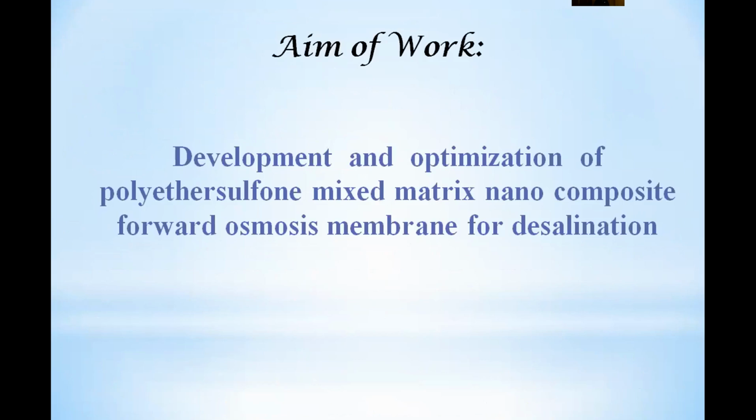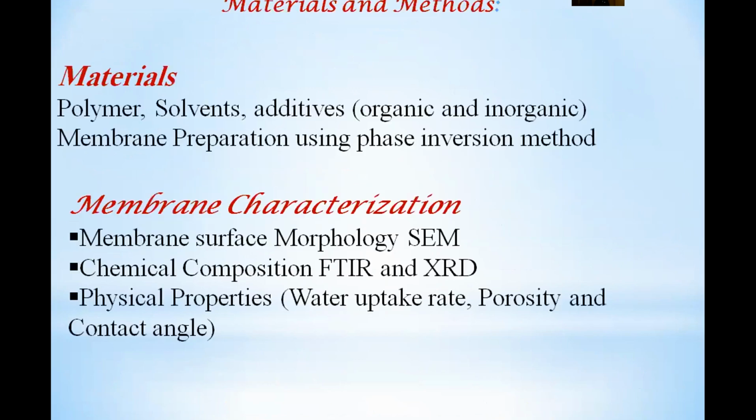Aim of work: development and optimization of a polyether sulfone mixed matrix nanocomposite forward osmosis membrane for desalination. Materials used in this work: polymer, solvent, and additives, both organic and inorganic. For membrane preparation, we use the phase inversion method.